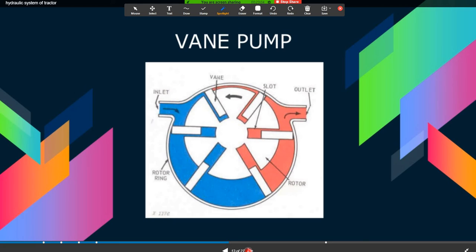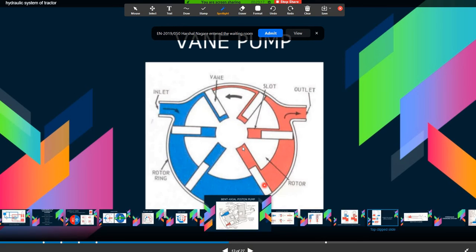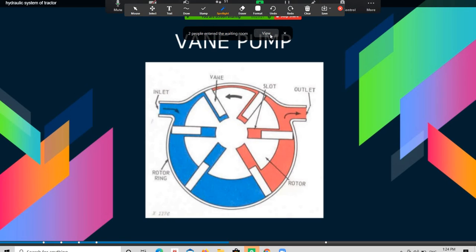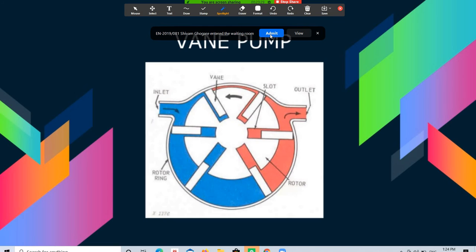And when the rotor turns, the liquid flows in between its side and casing and is trapped by the vanes, which force it from the inlet to the discharge. Generally, the vane pump is considered somewhat superior to the gear pump in terms of capability,